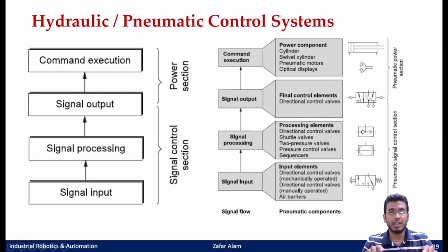Because see, pilot operated valve, because most of the signal elements, when you are pressing the push button, you are actually giving a two pressurized line coming from here. When you are processing a signal, again what would happen, two pressurized line is going through an AND valve, and ultimately the output you are getting, again you are getting a pressurized line, right?